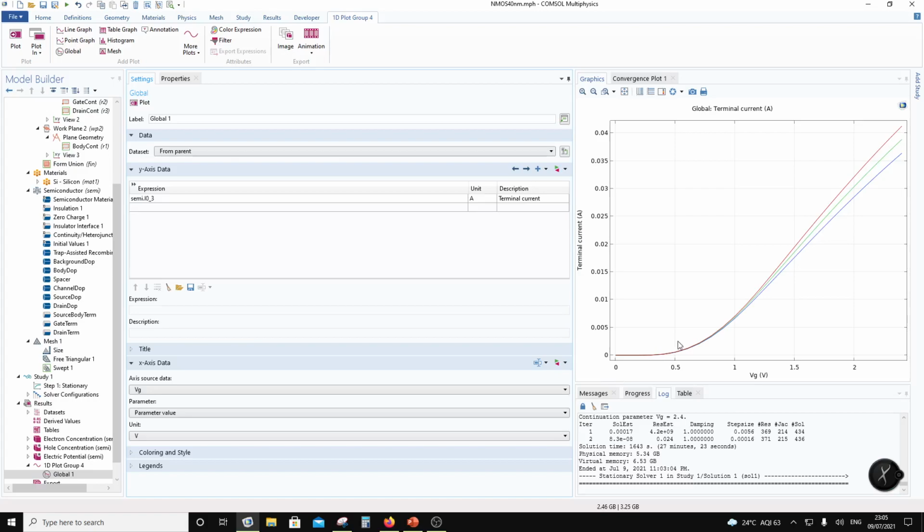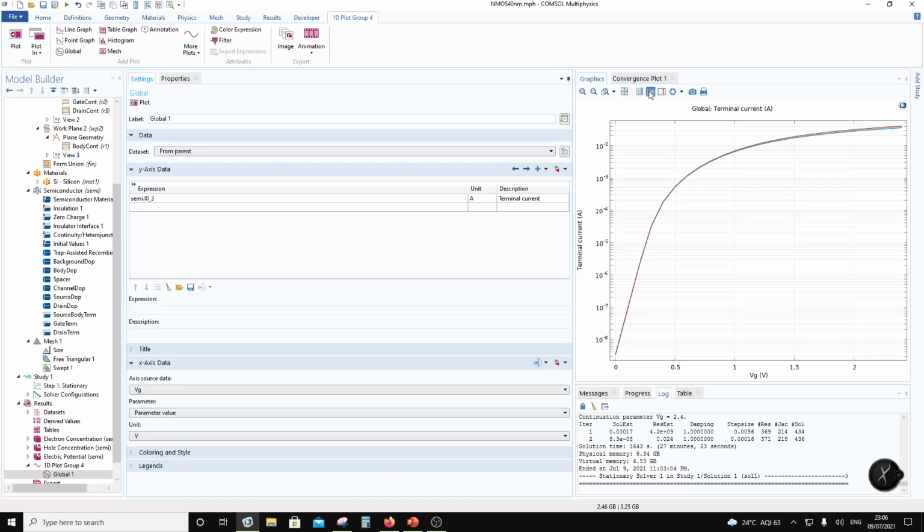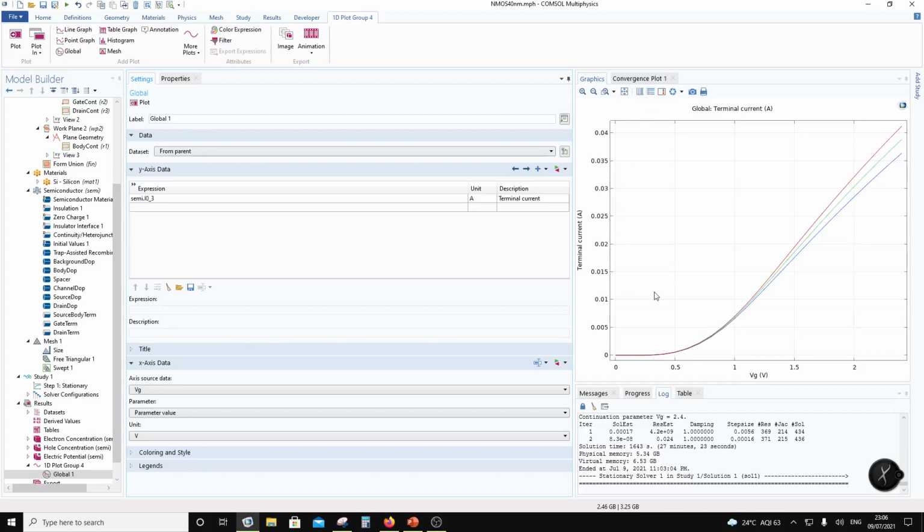So what do you see? You see mobility degradation over here, and if I want to find out the slope over here in the linear region, that will be my gm. This will be your threshold voltage, and if you go way to the left, you are going to look at the sub-threshold leakage current, which is the cause of all the static losses in your gates, right? So this is your transfer characteristics for this MOSFET, right? And the currents are around 40 milliamps. Yeah, so the device size is 2000 divided by 40, so 200 by 4, so that is going to be 50. So 50 is W by L in this case.